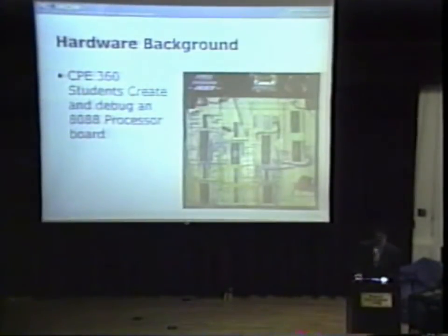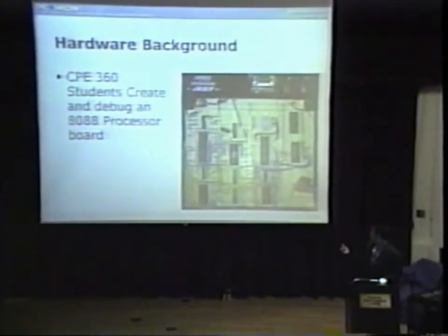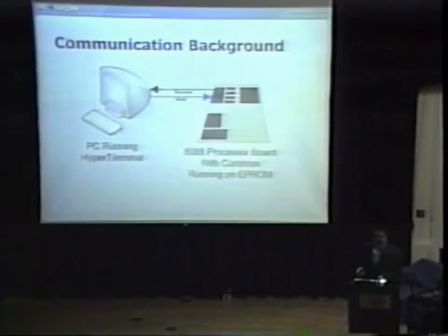In CPE 360, the students create this board right here. You have the 8088 processor, the EEPROM, which you run programs out of, and then a RAM, which you can store data on, and of course some blinking LEDs. The communication background: right now we use HyperTerminal on the PC to send commands to the monitor running in the EEPROM. The EEPROM then executes those commands and sends the result back to the computer. This is all text-based.